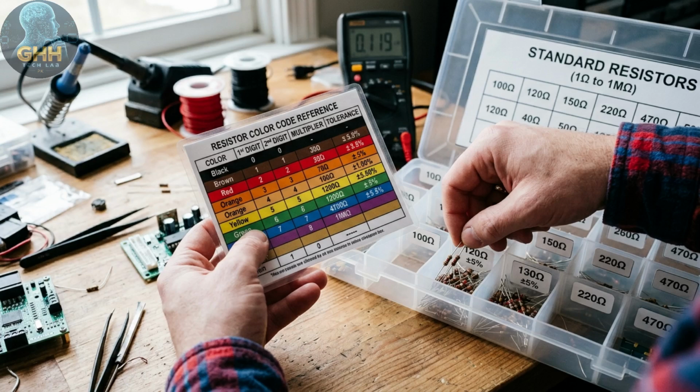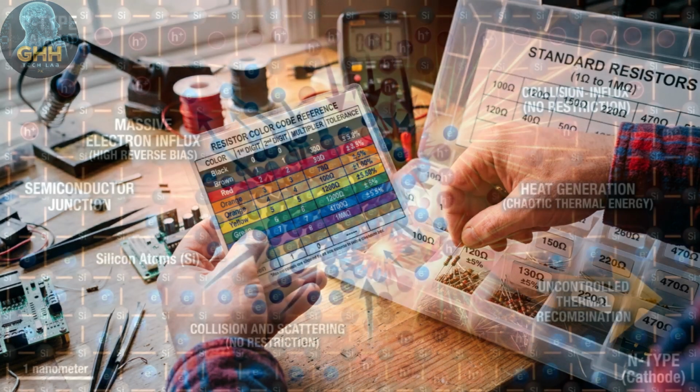If you don't have an exact 150 ohm resistor in your kit, don't worry. Simply round up to the next nearest standard value, like 220 ohms. Your LED will shine just as bright, and your circuit remains completely safe.